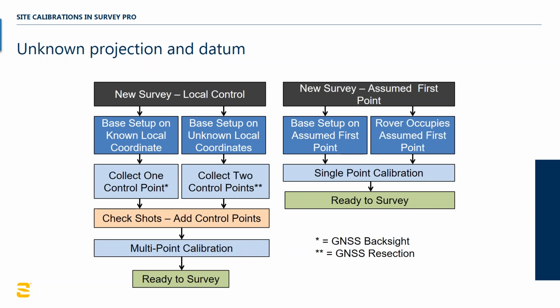Again, you might do something, you might change a rod height, or you might recalibrate with additional control points that changes the current solution of that point coordinate in the survey, but the stakeout report will always show what was shown at stakeout time, and you'll receive a warning. That point will be flagged, and it'll say, hey, this stakeout point is no longer where it was when the stakeout happened. Just emphasizing the point, we should get the calibration completed before we do any stakeout.